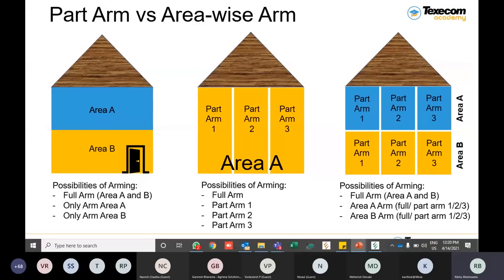So stay arming or part arming means I want to bypass the PIR motion but activate all the other sensors on my ground floor area. I'm not talking about the first floor area. Are you understanding what I am saying? I'm talking only about the ground floor area. I'm arming the ground floor area, but still bypassing one of the zones, which is the PIR motion. This is called part arming, meaning you are arming an area within the area.